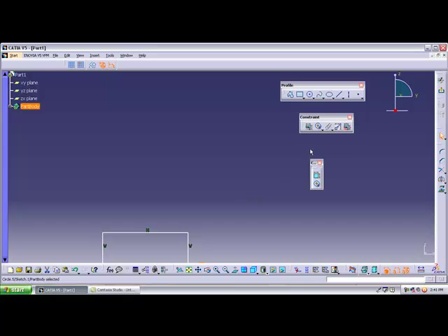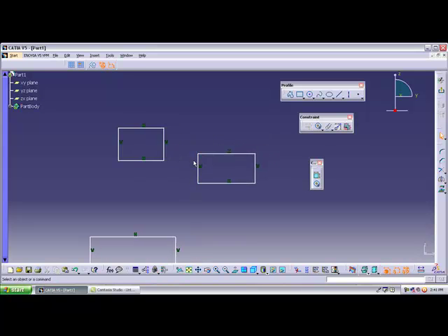And the next one is fixed together. Fixed together means, suppose I didn't apply any geometric constraints and dimensional constraints between these two rectangles. I didn't apply any constraint between these two things, so there is no relation between them. But what constraint do I want to make? I don't know the distance between these two things, but it should stay the same, it should be fixed.